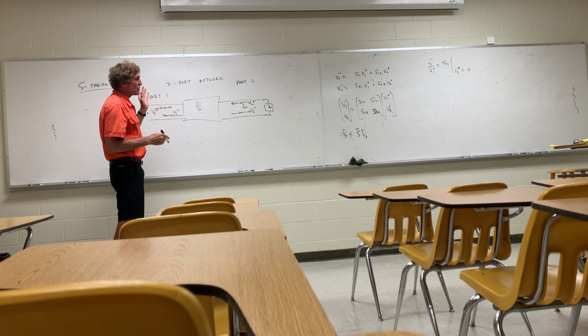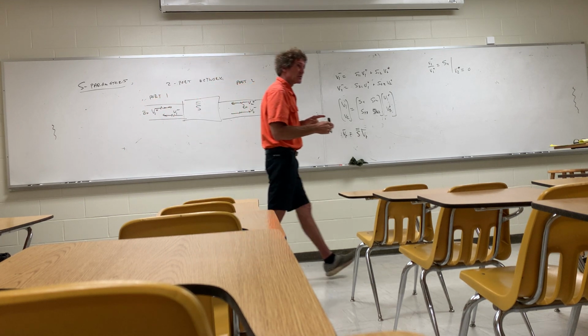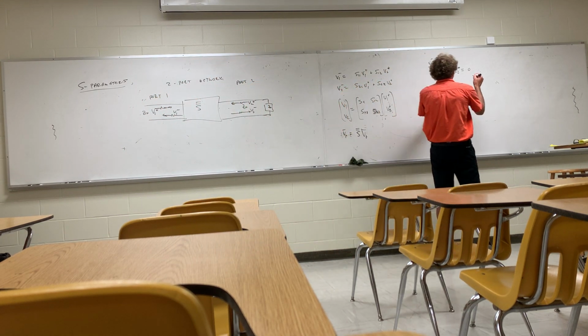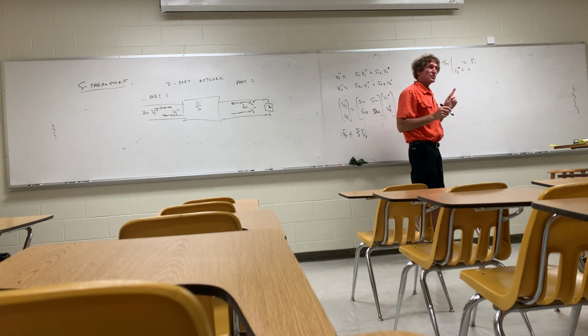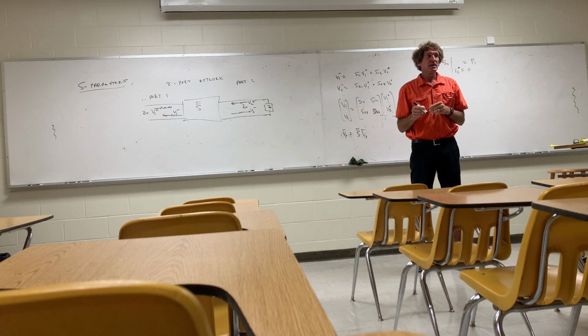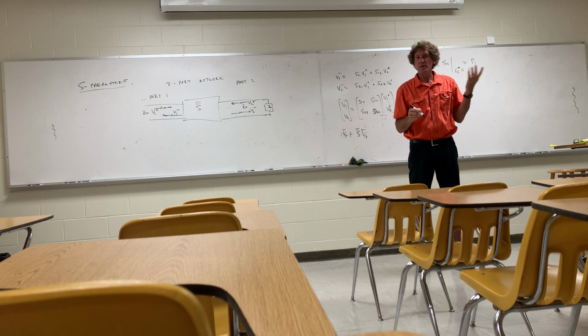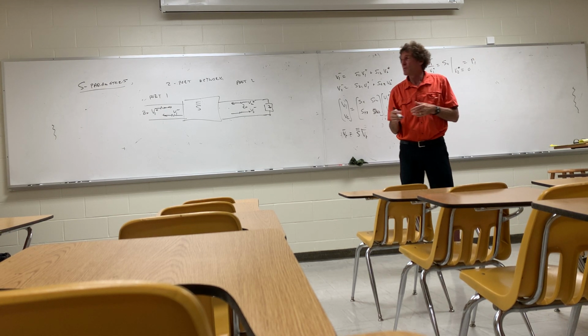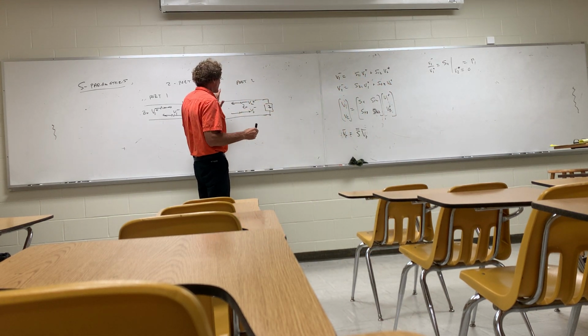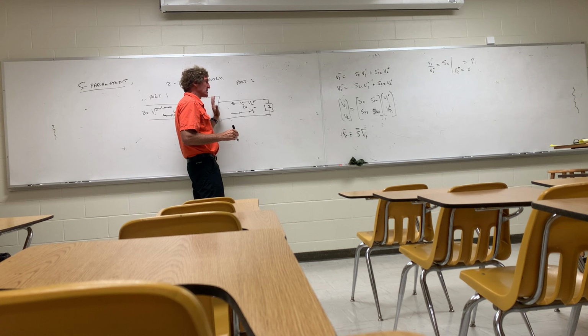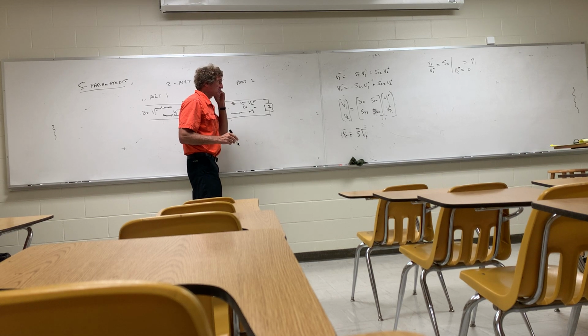So this S11 right there is the reflection coefficient. It would be the reflection coefficient at port 1, assuming V2 plus is zero. You all follow me? And the way you do that is just put a matched load condition on that. That way there can be no, I'm assuming there's no active generator here, but what happens sometimes is V2 minus comes out, hits something, reflects back, so you have V2 plus. Just keep that in mind. So that's the reflection coefficient.